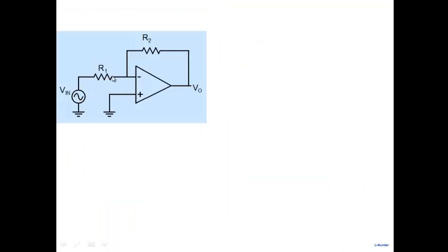We make an amplifier that you see here, a normal inverting amplifier. But we don't say that the gain of this amplifier is R2 by R1. That R2 by R1 is based on the fact that this point is virtual ground, which is no longer true, because we know that if you go to sufficiently high frequency, the op-amp's gain is very low, and this point is not virtual ground.